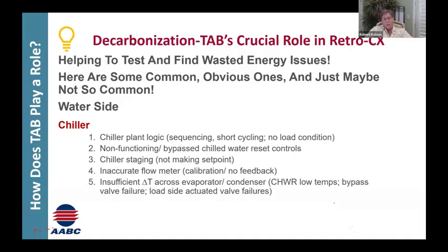The field data that's recorded is the driving force in the development of the corrective measures necessary to bring the chiller back into proper operation. So we would take the actual load across the chiller, DPs across flow meters, verify offsets which, Robert, may be necessary in our diagnostic testing.